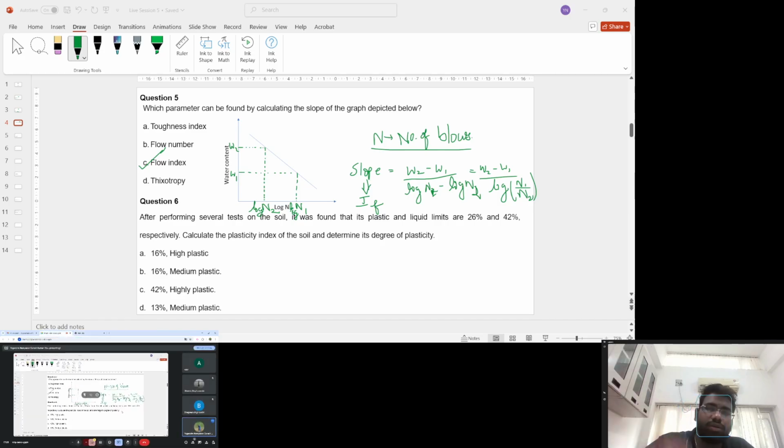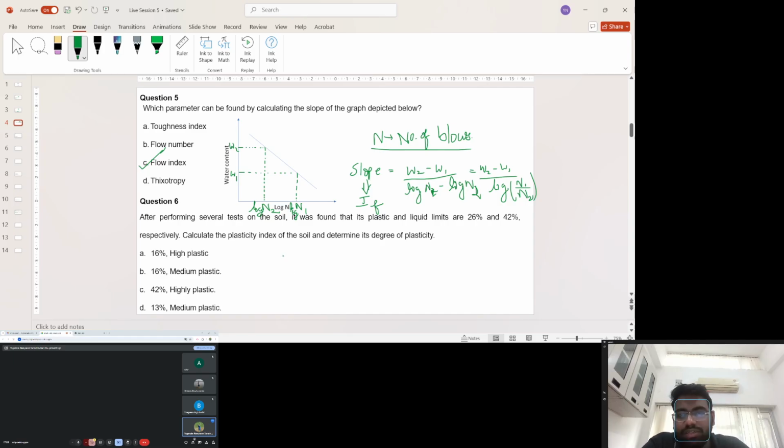Yes, sir. So plasticity index IP is defined as liquid limit minus plastic limit. Now 42 minus 26 will give us 16%.